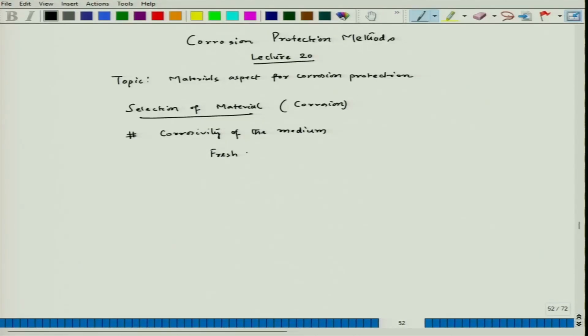Okay. So, if we consider these two cooling waters, fresh water as well as polluted fresh water, here we have copper ion, let us say, or Fe 3 plus ion. If we try to see the corrosion effect on aluminum, this can lead to a serious pitting on aluminum.